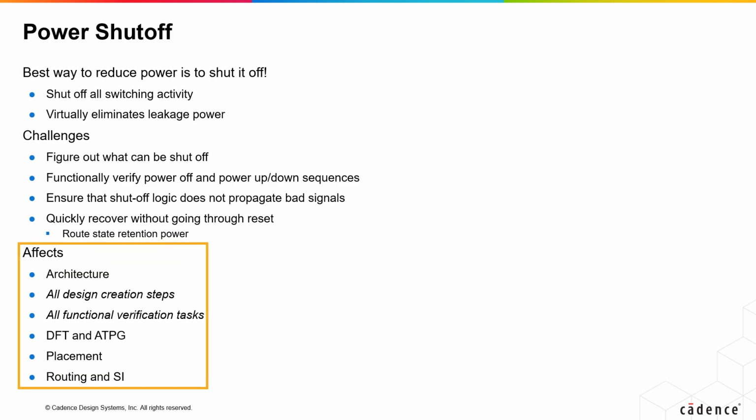Power shutoff methodology affects the architecture and all the design creation steps. It also affects all functional verification tasks, DFT and ATPG, placement, routing, and SI.